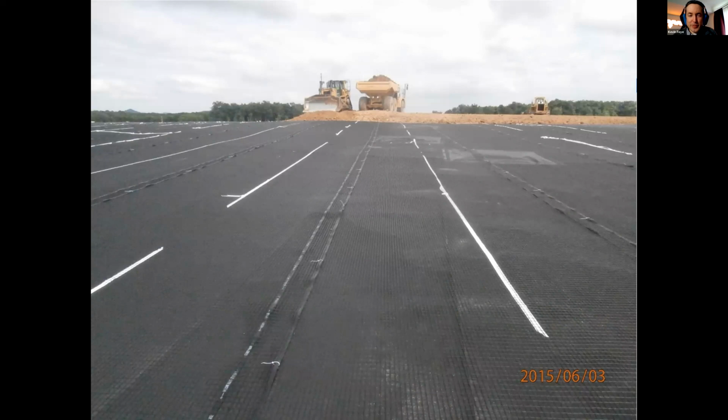So before I go to my conclusions, I want to share some photos of what this looked like when it was being constructed. I think it's important to understand how these get built. What I'm showing in this photo is one of our layers of Geogrid that had been deployed above the geomembrane. You can see the geomembrane below. You can see the Geogrid above, oriented in the direction where we're expecting the major depressions to occur across the trenches. And then you can see in the background trucks that are deploying soil. So you have trucks dumping on the area where soil has previously been placed, and bulldozers pushing and deploying that over the cover. So this is the cover system going on.